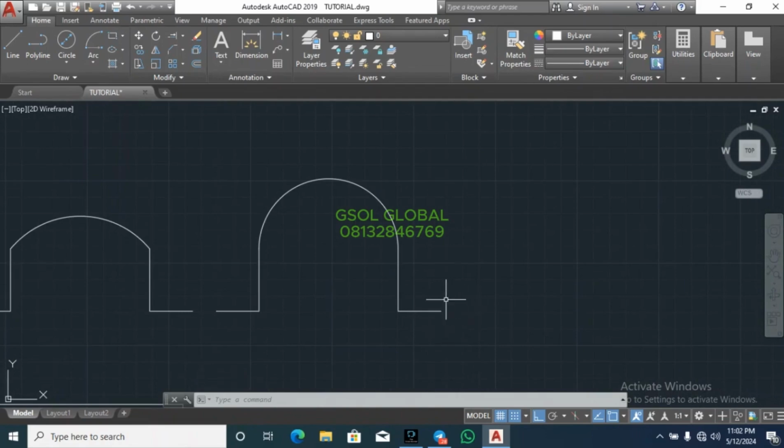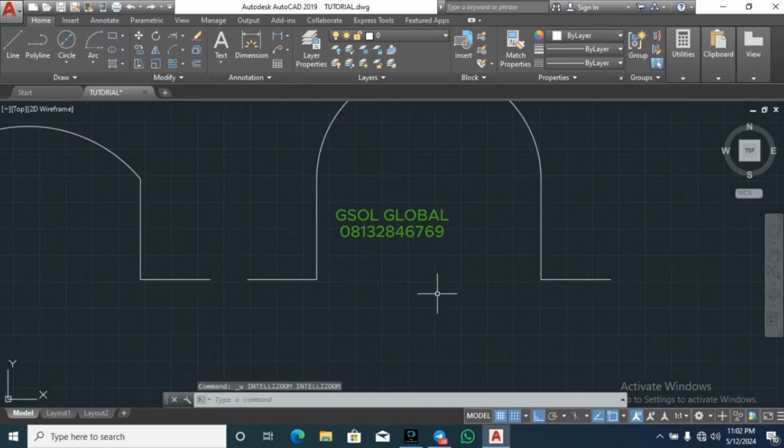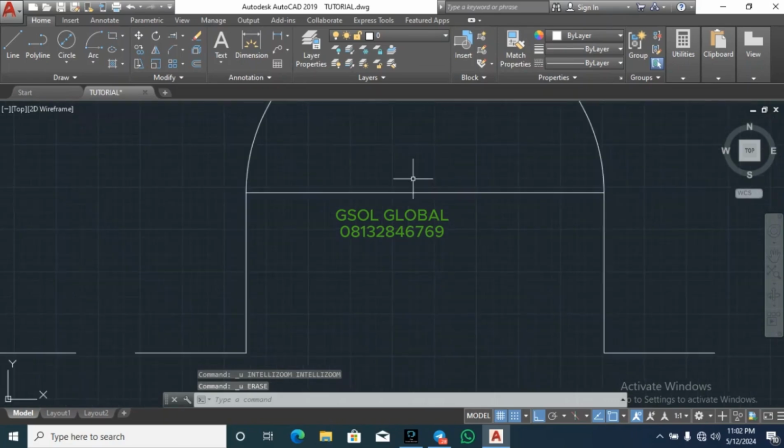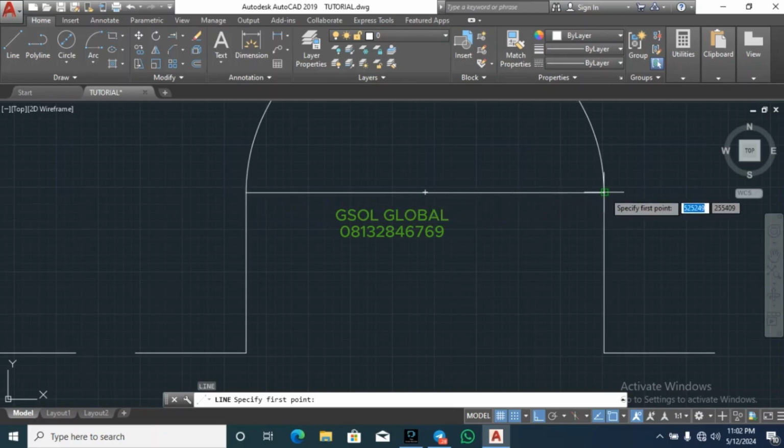So let me address something here. There's what we call O snap. In case you are trying to work on your drawing, let me go back. Let's assume I want to modify, or I want to select a particular part of this line. You can see different points. This is your green triangle symbol, the green square. You see those things, they are just O snap. So you can use them to select different parts of the line.